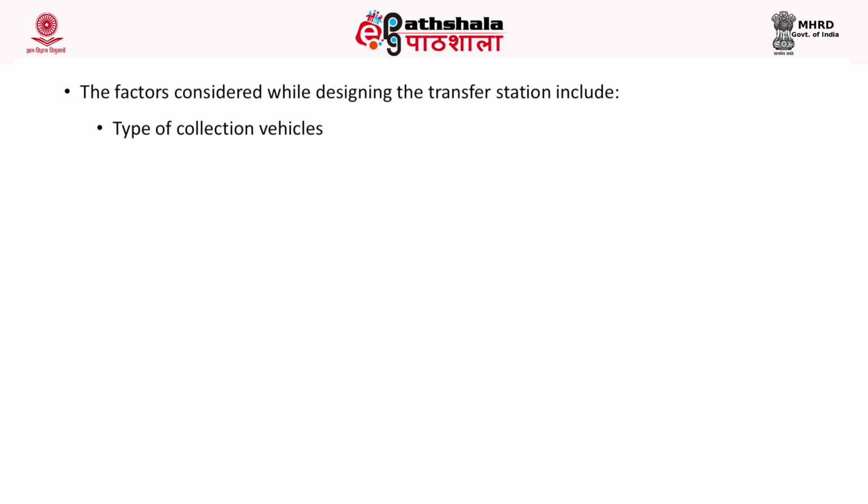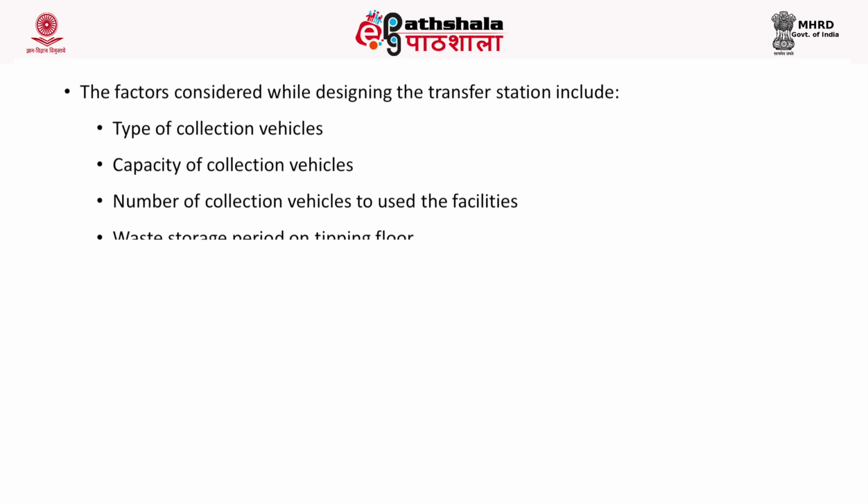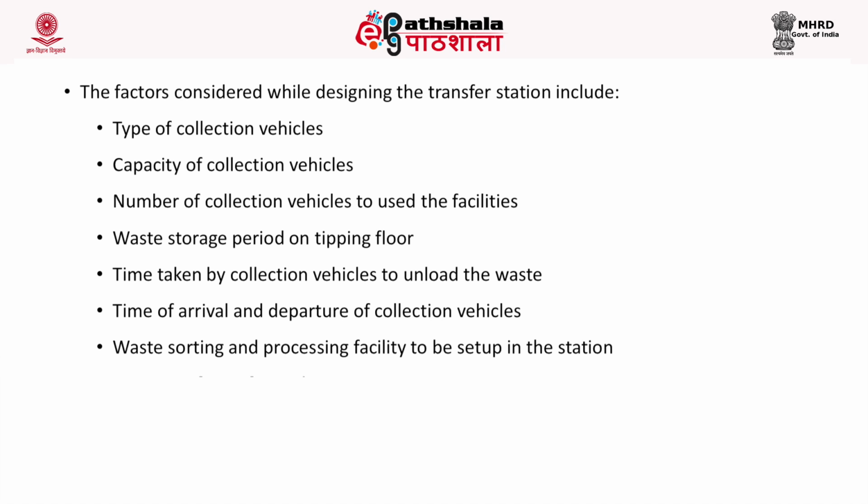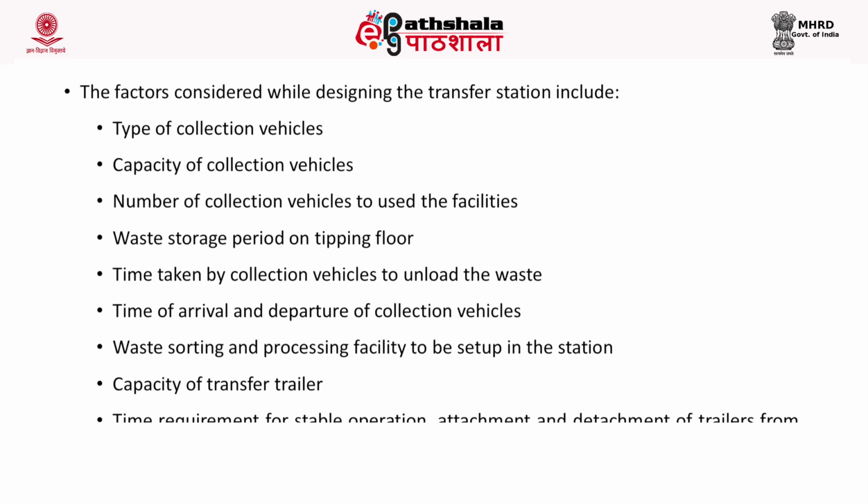Now, the factors considered while designing the transfer station will include the type of collection vehicle, the capacity of collection vehicle, number of collection vehicles that will enter the facility, the waste storage period on tipping floor, time taken by the collection vehicles to unload the waste, time of arrival and departure of these collection vehicles, waste sorting and processing facility that is to be set up in the transfer station, the capacity of transfer trailer, the time requirement for stable operation, attachment and detachment of trailers from tractors and compactors should be considered.